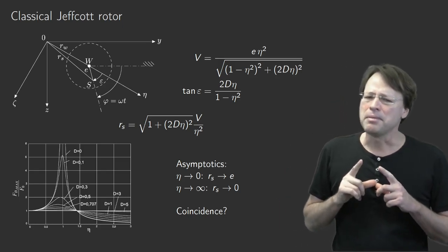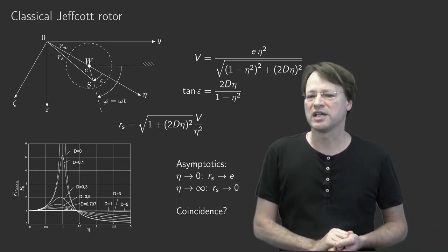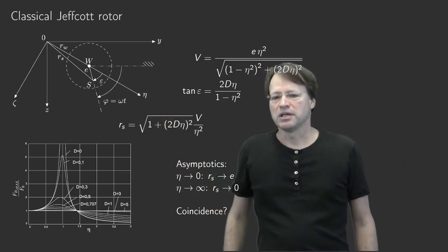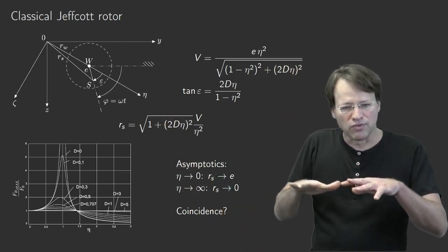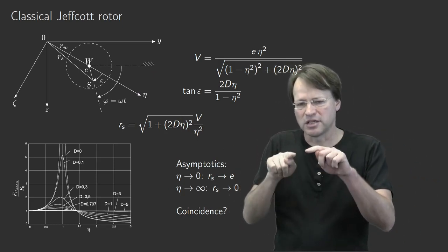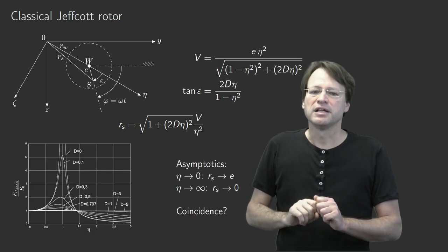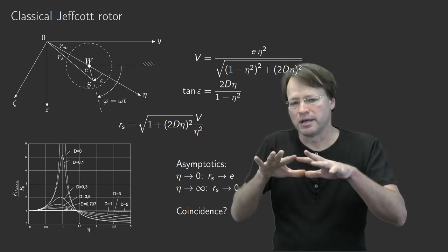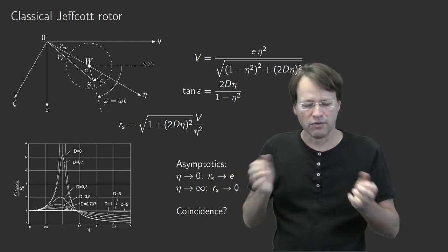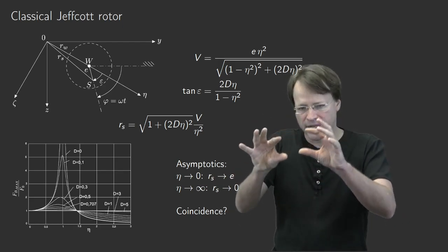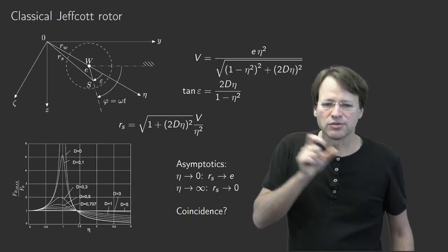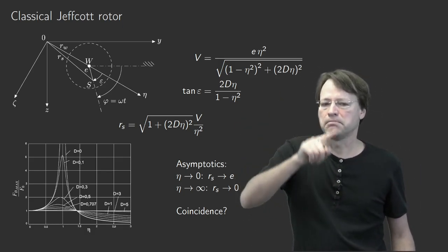Maybe the best thing to understand why we get this is to think of that system as being a problem of vibration isolation, where you have a spring and a dashpot damper that connects the center of the bearing to that rigid block of mass. That rigid block of mass represents your rotating imbalance.